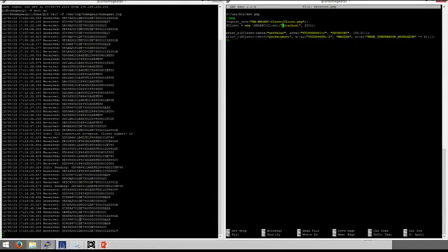And as you can see, we are sending two RPC functions. The first one is setValue to the thermal control we just created in HomeGear. You remember we named it VTC1. The variable name is setPoint. Again, this information is out of the XML file. And we set setPoint to 100. 100 is a special value, meaning always on.